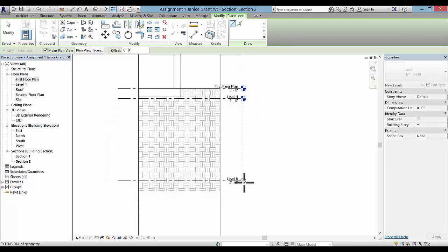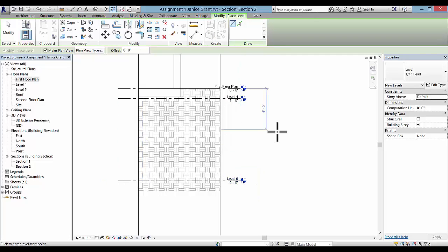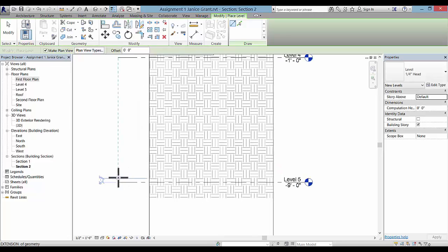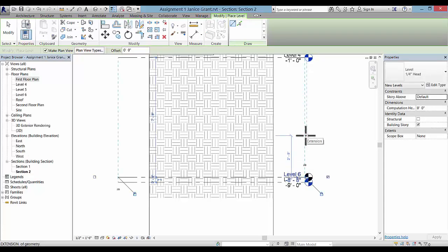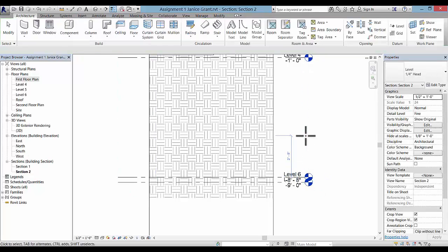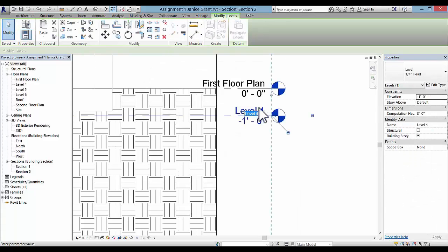So we'll go 8 foot more. And one more that we should create is the basement floor that we can work off of. And we can make that one 4 inches here as another level. It depends on your wall section. It could be different for commercial drawing. So we can rename this level 4 top of, or TO, foundation wall.